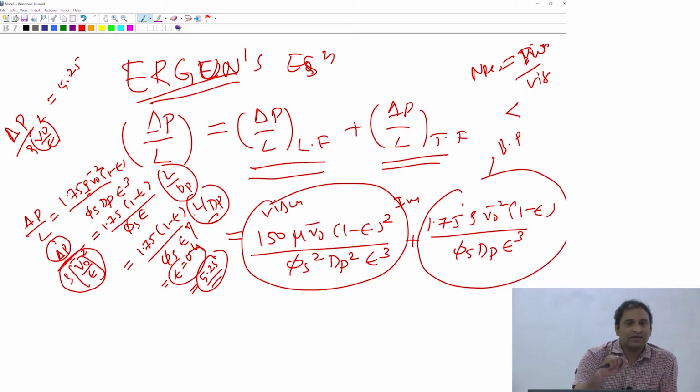It tells you, for every layer of particles in the packed bed, what the pressure losses are compared to the head losses. The fact that this pressure drop is 5.2 times the head losses means the kinetic energy losses in turbulent flow conditions are much larger.